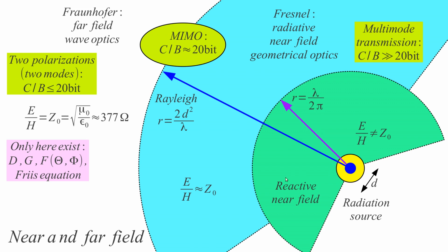And here is where the reactive near field is very good. A thief who would like to steal our money cannot create this strong near field at any practical distance. So the bank card only works over a distance of perhaps 10 centimeters. It is completely deaf at 1 meter distance because of this reactive near field decaying so quickly with the distance.